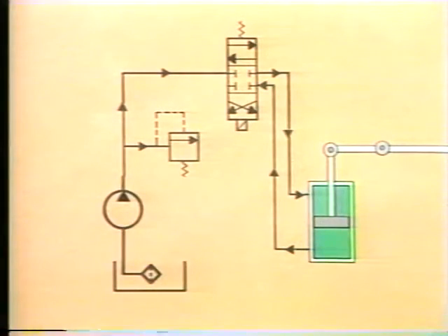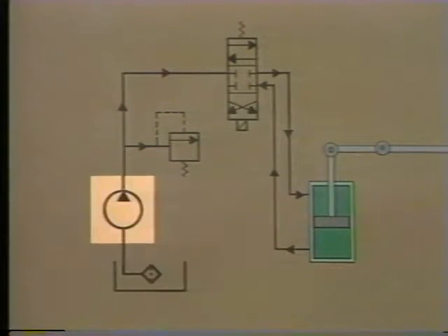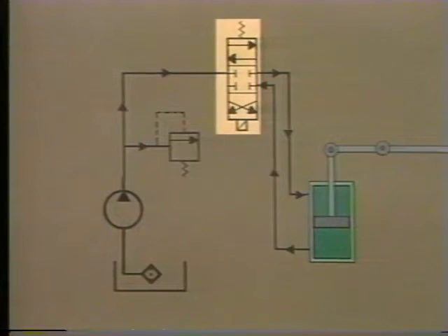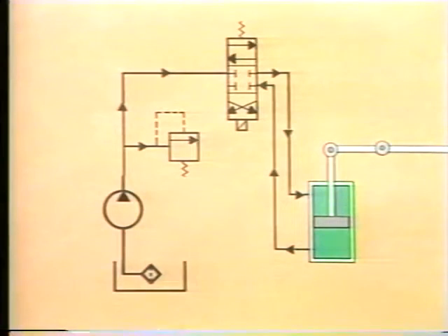Now that we know the major differences between the two fluids used in fluid power systems, we're ready to look at some system prints. We'll use this print of a simple hydraulic system to start with. This system has a reservoir containing hydraulic fluid, a pump, a pressure regulating valve, a directional control valve, and an actuator, a piston and cylinder that are used to perform some sort of work. It's important to note that although plant prints often contain symbols that represent both piping and tubing, the interconnecting lines on fluid power system prints usually represent tubing rather than piping.